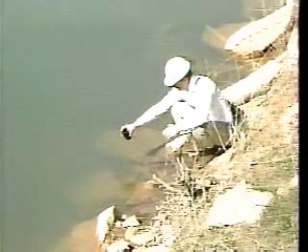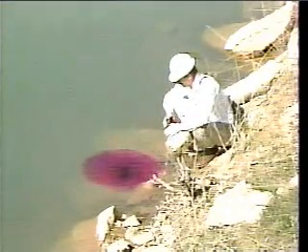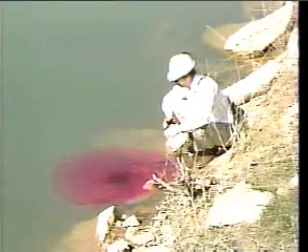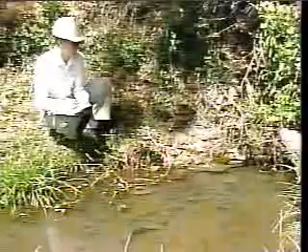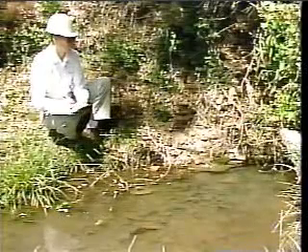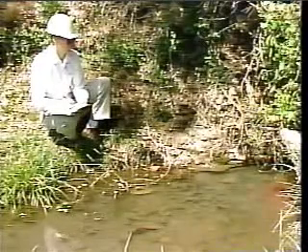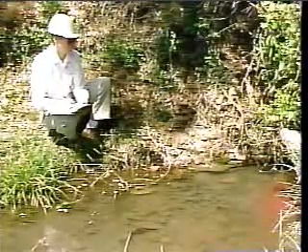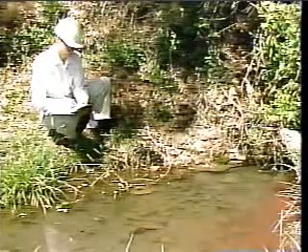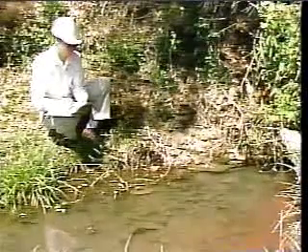A dye test for seepage can help you determine the source of seepage. Let's see how to do that. First, place the dye in the reservoir at the location where the seepage is suspected of entering the foundation or abutment. Then, check the downstream seepage points. In this case, we can definitely see the reappearance of the dye, confirming that the reservoir is the source of the seepage. Remember that you should record the location, quantity, and flow rate of all seepage points, as well as the level of the reservoir at the time of observation.